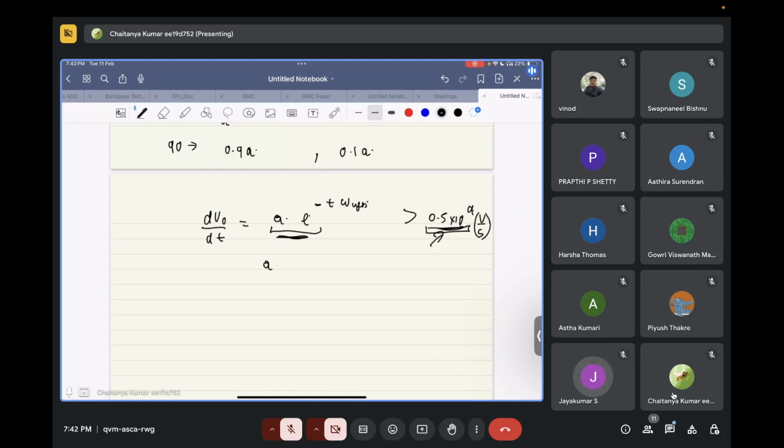Okay, but if this particular quantity is less than the slew rate, then the output will rise based on this quantity. So it's kind of an equivalent of a power supply saturation. As the voltage of the op amp saturates, the current for the op amp also saturates. The op amp can only source a finite amount of current. That depends on the internal structure of the op amp, and you will learn about this in some advanced level courses. But the current of the op amp also saturates.